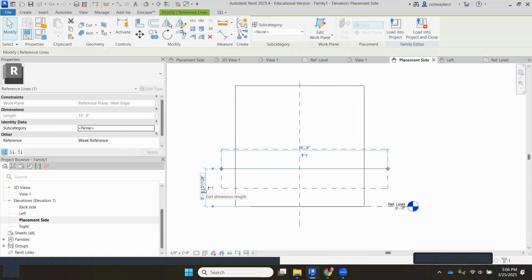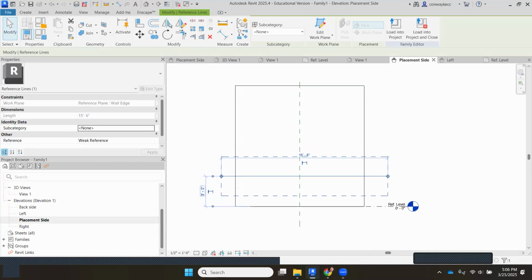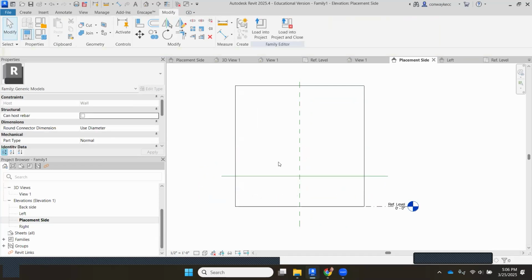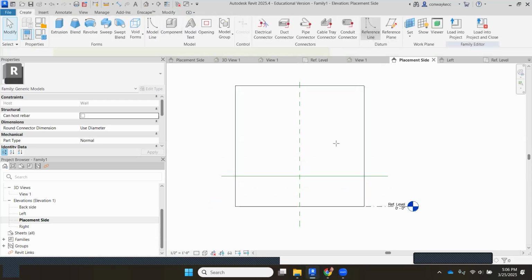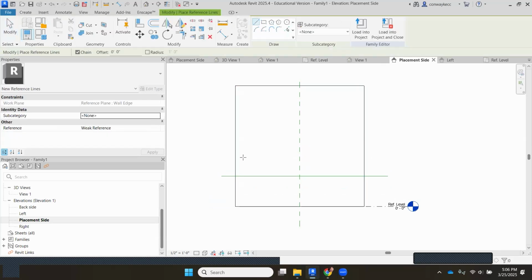We have the layer that's at 3 feet for the ADA accessible. So if I type here and make this 3 feet, that's roughly the height where that surface is. But most of you also have a higher, what's called a transaction counter, if somebody walks up and it's more at their chest level. So I'm going to put this line here. So that's 3 feet. That's generally at 1 foot above that.